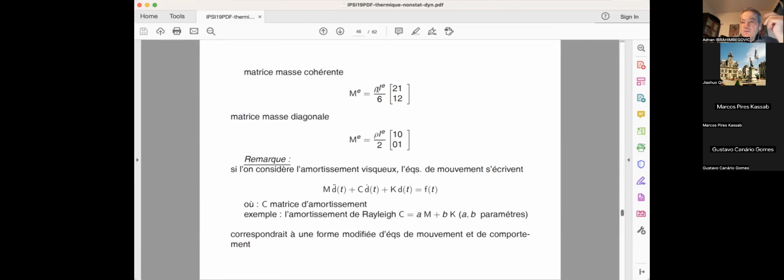If you talk about the explicit method, there's interest in using an approximation for such a mass matrix. And this approximation is done in many different ways. In the book of Zienkiewicz-Taylor, one of those early versions of the finite element method book, they discuss 2 or 3 different versions of diagonalizing this. But here the simple one is just physical. If you want to compute the diagonal mass, you simply move all these coefficients to the main diagonal.